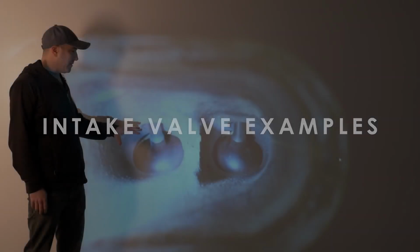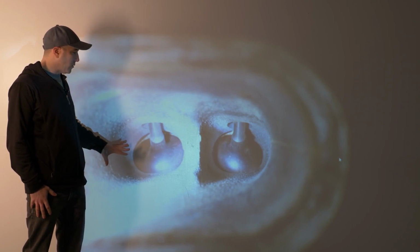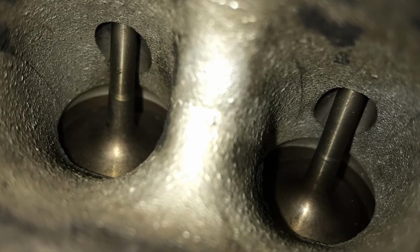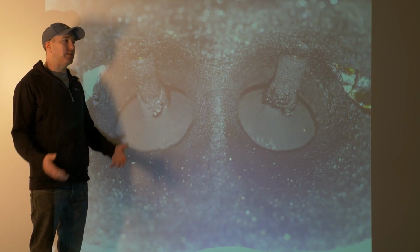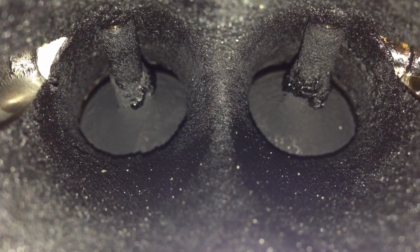Now, if you take the intake manifold off and stick a camera down those holes to the intake valves, this is kind of what a port injector car would look like. The valves are extremely clean. Or after a cleaning, of course. This is what intake valves on a direct injected car will look like after 30 to 60,000 miles, depending on the brand, depending on the motor. It's extremely variable, but eventually this is going to happen.